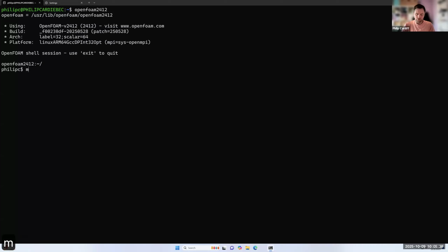So to create that run directory, you'll type mkdir, and OpenFOAM will already define a number of what are known as environment variables. So I'm writing the $ and then capital FOAM_RUN here. And then I'm going to type -p. So this thing is called an environment variable, which is essentially FOAM_RUN, and $ just means use the value of it. There are many of these defined by OpenFOAM, and this is just a shortcut for an address.